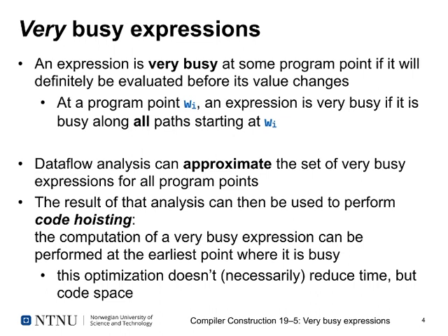This optimization isn't necessarily reducing execution time, so it's not in all cases a performance optimization. It can be, but it reduces code space, and this optimization can be very useful in small-scale embedded systems where the amount of flash space in read-only memory is very limited, so you need to ensure that the size of your code is actually as small as possible and you don't care as much about the performance of your code.